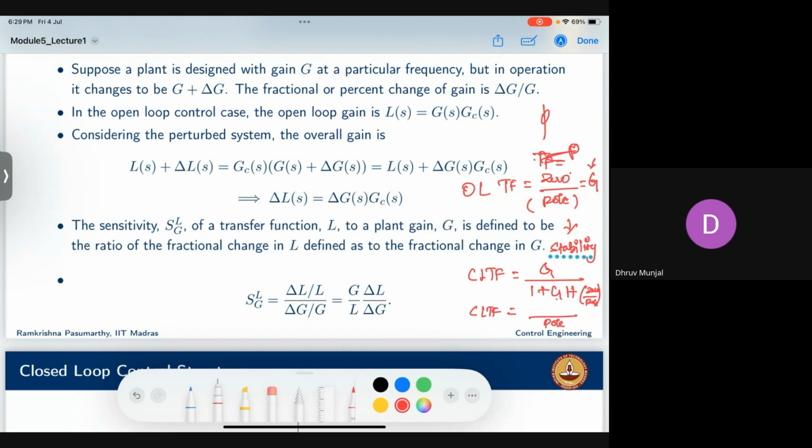This is in case of the open loop transfer function. So an open loop zero can act as a pole in the closed loop transfer function when you find the closed loop transfer function. So even if the zero is in the right half of the S-plane, when you try to design a controller using feedback as a closed loop system, that zero is going to affect your system stability because finally it is going to be a pole of the closed loop system. This is one point.